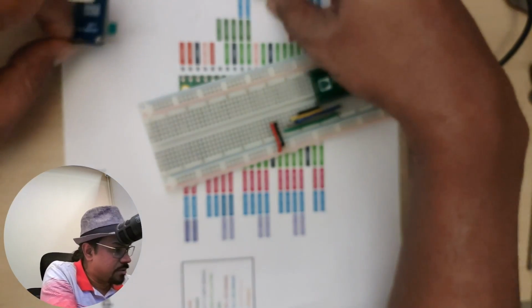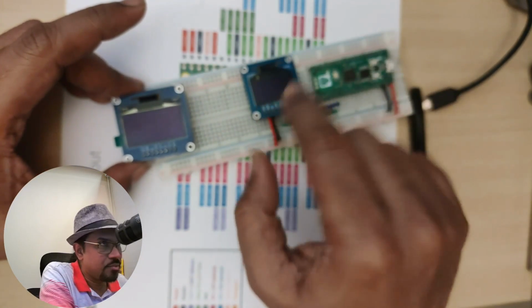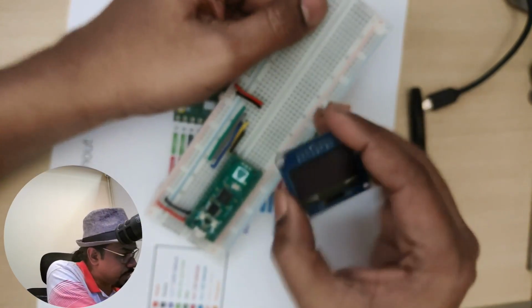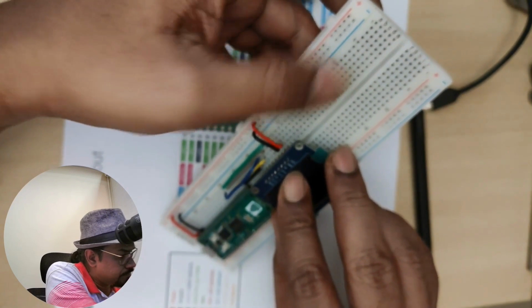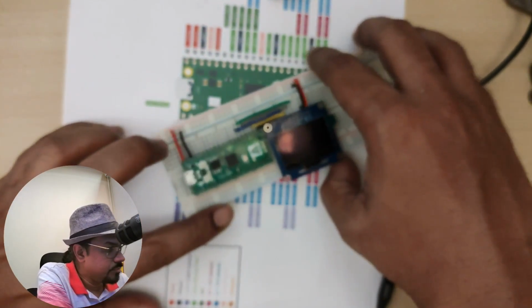I'm going to just drop in replace another display which I have here, yeah, the slightly larger one. You can see that. I just removed this display that was there. I'm going to use the slightly larger display, which is also the Waveshare display. It's all the same. The pinouts are the same. It's a drop-in replacement. You can plug this in. I'm going to do the same thing in here. I'm going to plug it in correctly to the positive and the negative. So plug this display in this time, which is a 1.3 inch display.